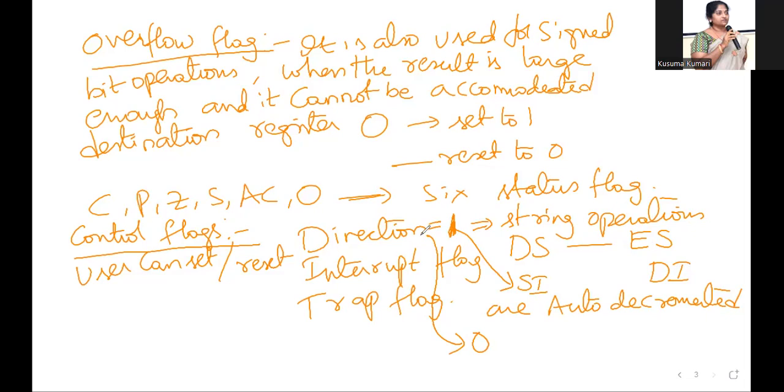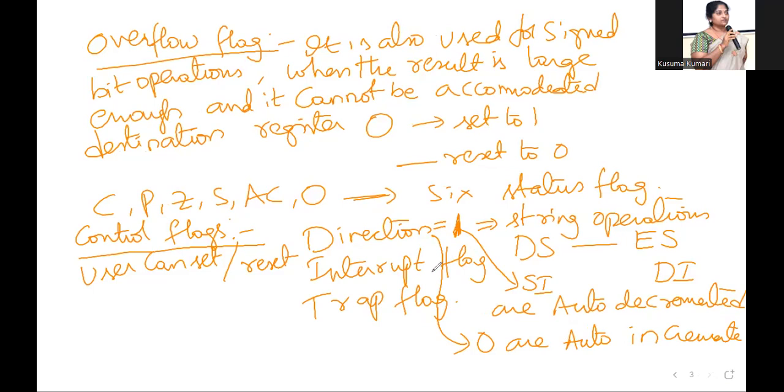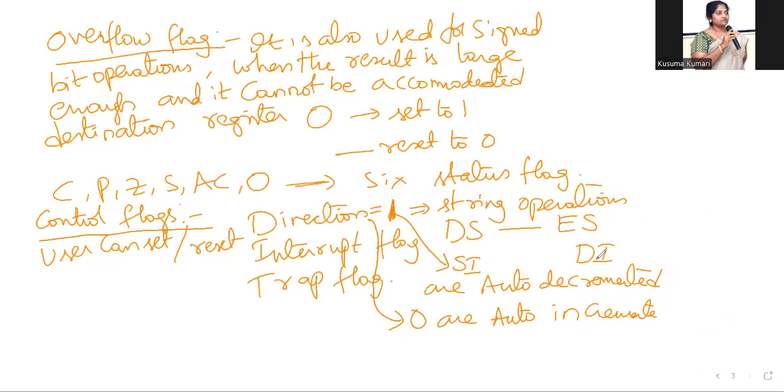But since the direction flag is equal to 0, these two register contents are auto incremented until the string operation is performed. Okay, that is about the direction flag.